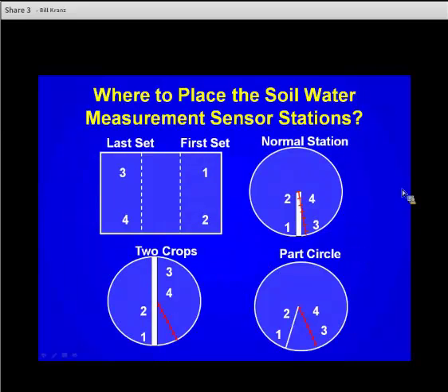Placement out in the field, when we get to that point, these are images of drawings of what our traditional approach had been, utilizing tensiometers or Delmhorst soil blocks before. And you certainly want to get some idea, if you're in a furrow irrigated area, what the soil water content might be at the top and bottom of the field, and also in different sets, so you can plan ahead in terms of when you need to be across the field. In some cases, with furrow irrigation, you may have to start irrigating before you really would like to get that done.